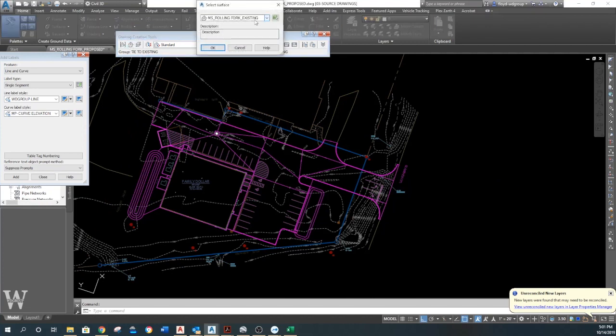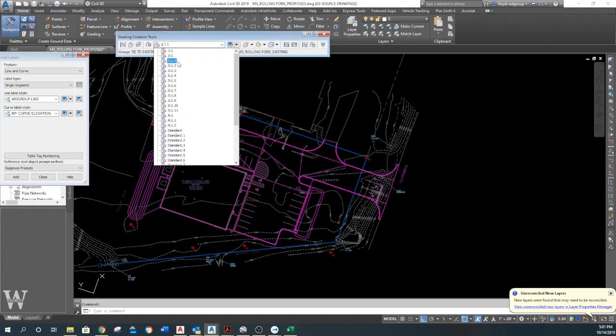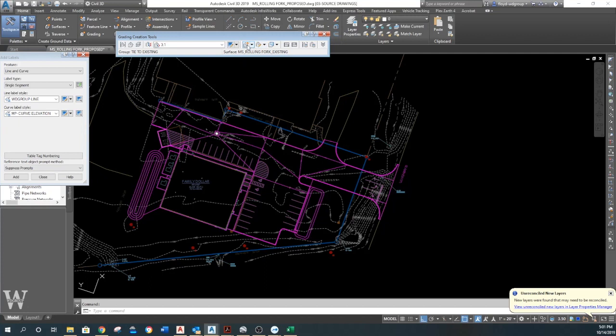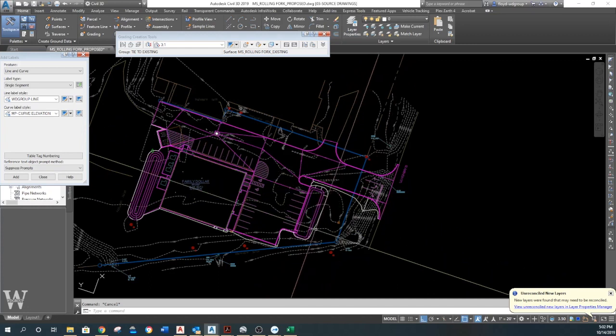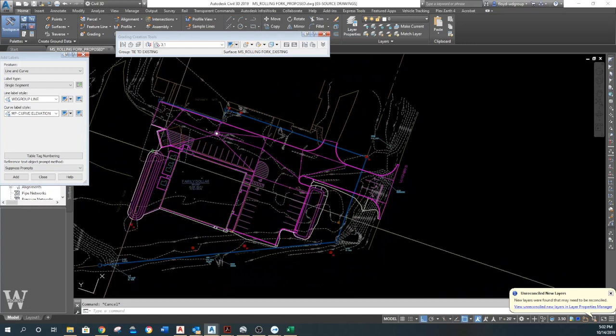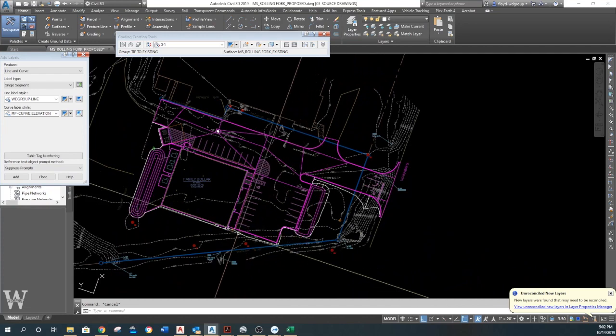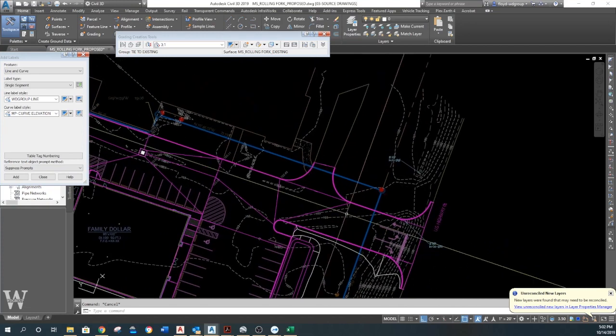We're going to hit what surface do we want to grade to? The existing surface. We're going to do a 3:1 slope. So now we're going to click on that. Click on the line, select the grading side, apply to the entire length, yes. 3:1, 3:1, cut and fill. Voila. It'll draw us a little line around here. Okay. And all I care about is make sure this white line, when it came here, stayed inside my boundary, and it did.